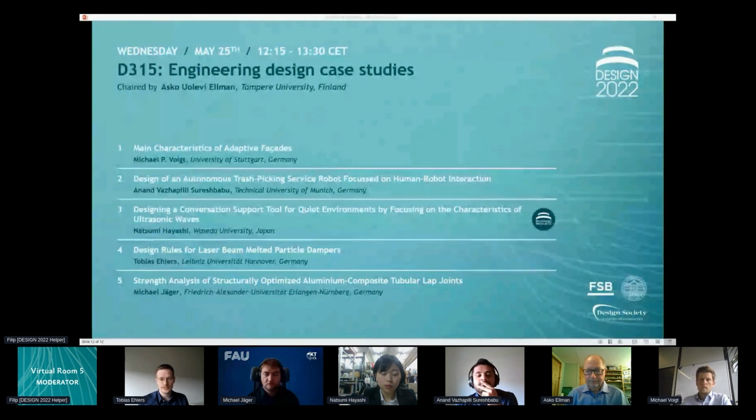To the second question, at our institute, we also have a multi-material printer, so we can print or leave unmelted powder with different powder inside the beams. That means when I have a beam made of aluminium, I can also put tungsten inside the beam. That is a material with a high density, and so I can achieve a lot more damping, which I cannot achieve with an increase in the cavity volume.